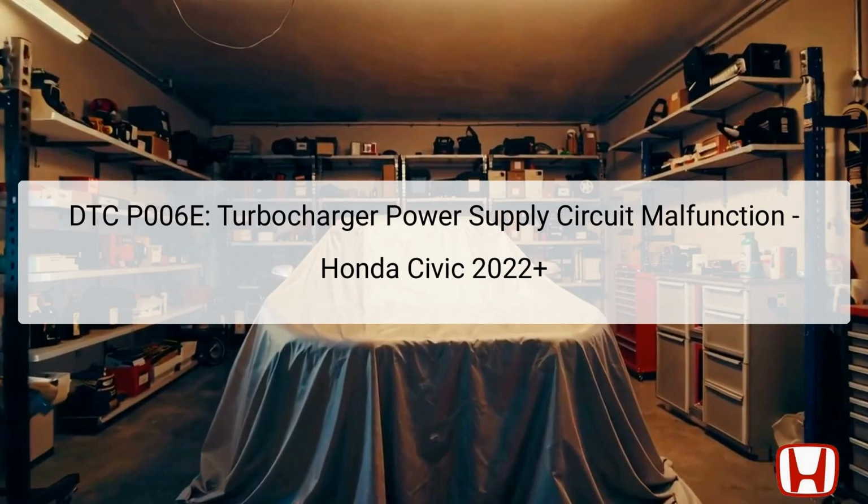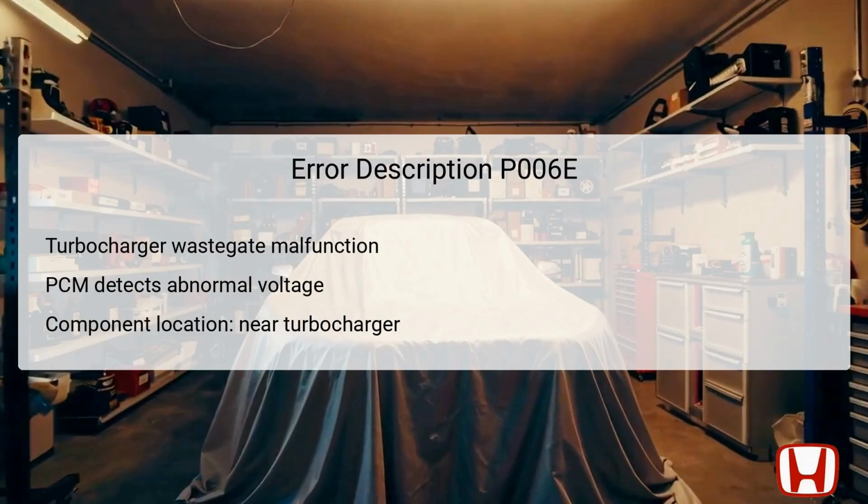optimal operation. DTC P006E signifies an issue with the turbocharger wastegate control actuator, primarily focused on its power supply circuit. The PCM, or powertrain control module, monitors this circuit continuously to ensure it delivers adequate voltage. When it detects a voltage lower than a specified value, it registers DTC P006E.